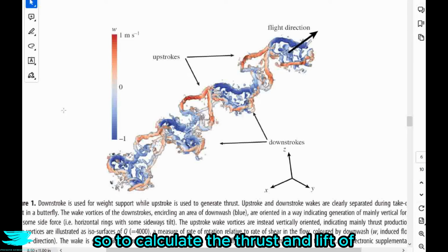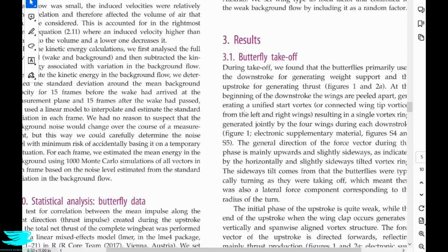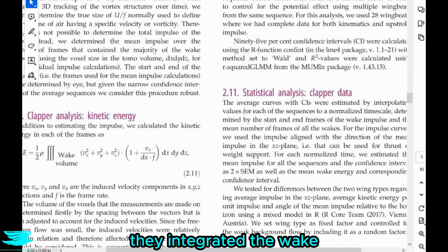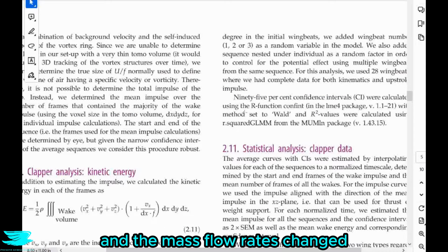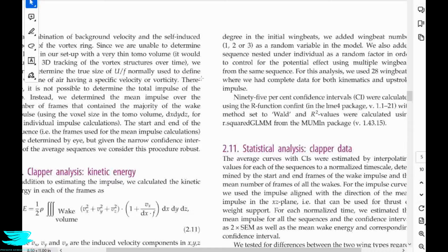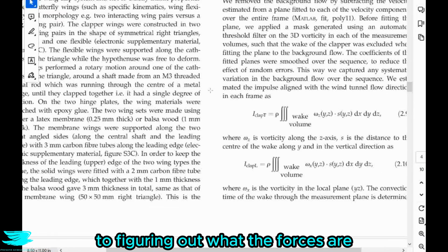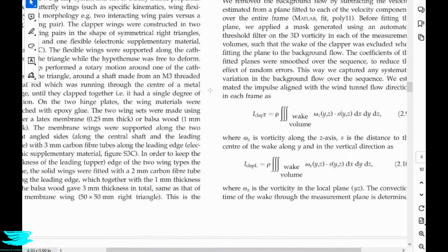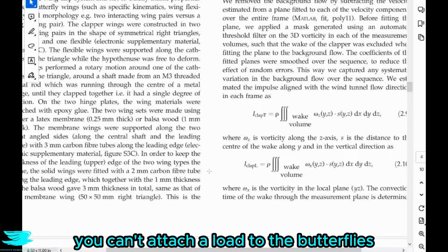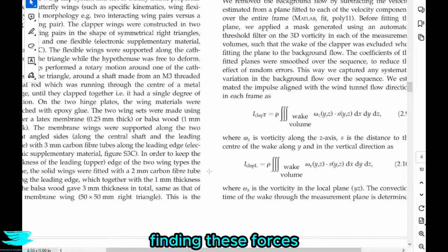So to calculate the thrust and lift of the butterflies when they were flapping around, they integrated the wake to see how much the velocities effectively and the mass flow rates changed. And this is really cool because you rarely see such an approach to figuring out what the forces are of an object based on the wake. And obviously you can't attach a load cell to the butterflies, so integrating over the wake is also a very good way of going about finding these forces.